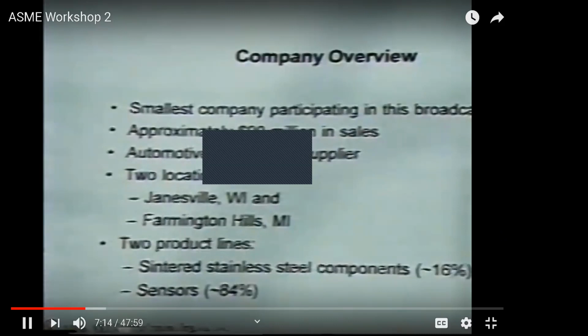Brake assist was not there in 1989, but that is a new application mainly for the European market where they want to have brake by wire. Air conditioning systems, automated clutches, power steering, stored gas for some of the newer airbags where rather than using a detonating device, some people want to use a stored high pressure gas in order to activate the bag in a more gentle fashion. Turbo boost for some performance monitoring of the engine, and finally tire pressure for both safety and run flat tires.